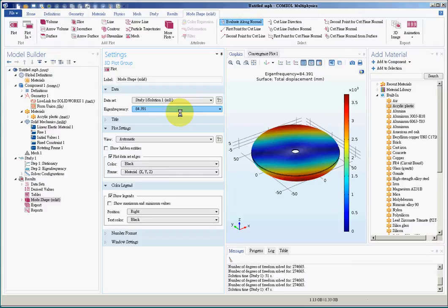So the external load does not affect the natural frequencies, because the external force term appears on the right hand side of the ordinary differential equation. But once the external loads generate a substantial increase in prestress or internal stress, the stiffness or rigidity of the structure will increase, and thereby increase the natural frequencies.